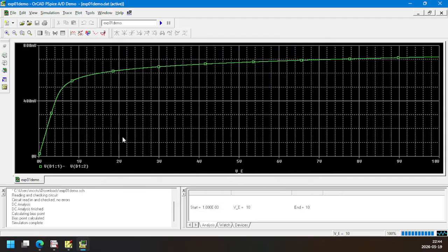Okay, I click on OK, and I see that the voltage is actually not increasing that much. Previously it was increasing gradually, but the voltage is kind of fixed after some time, around 0.7 volt or something. So 0.4, 0.5, 0.6, and 0.7. For a silicon diode, the voltage across the diode is kind of fixed, which is 0.7 theoretically, but practically we see that it is gradually increasing and kind of saturated around 0.7. So the voltage across the diode is actually 0.7.